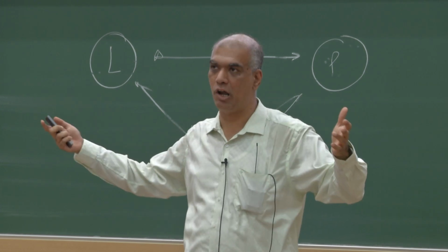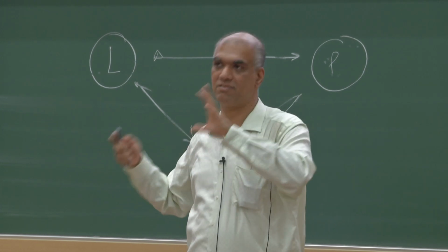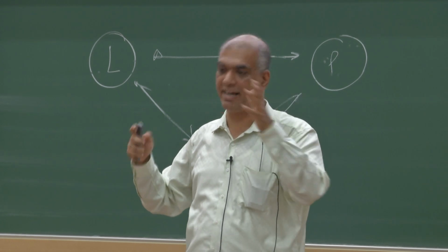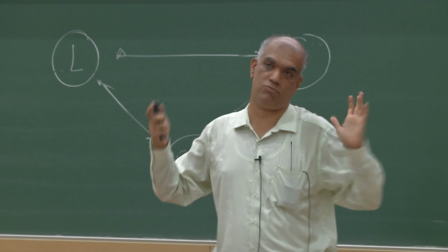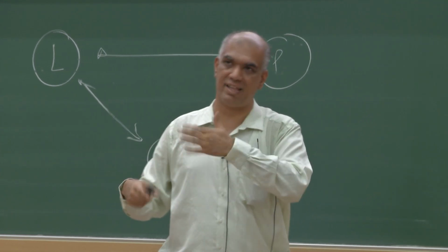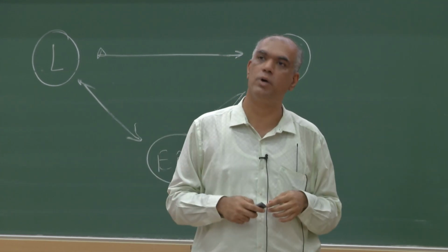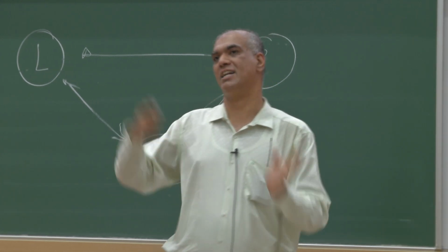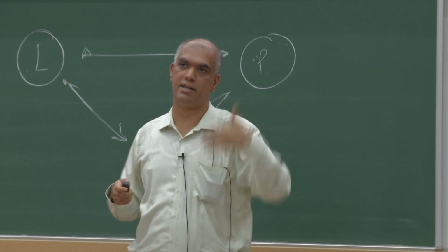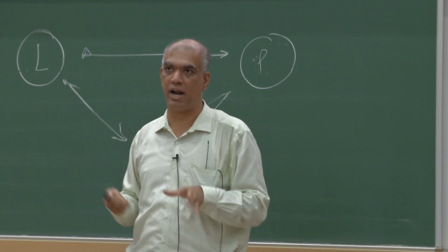Suppose it's a distillation column. Have a drawing of the trays. Whatever you're designing, once you have designed it, represent it. And I'm not saying do 3D, do a 2D drawing. 2D drawings are also great. Now, if you do a 3D, you can automatically ask the software to do a 2D, but do a 2D drawing. But do a proper mechanical drawing, because that's what your fabricator is going to want if you are actually going to build a plant from this.